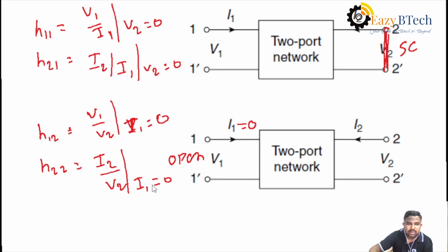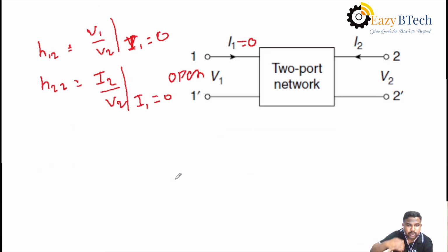Then like that, for the given circuit, based on the standard equations of H parameters, you have to calculate the required H11, H12, H21, H22. Then after calculating all the parameters for the given network problem, you must represent the parameters in matrix form compulsorily. Then after finding the H parameters, what are the main conditions for reciprocal and symmetrical?